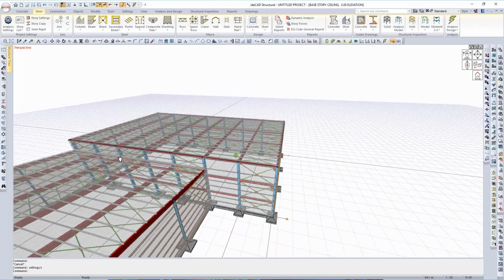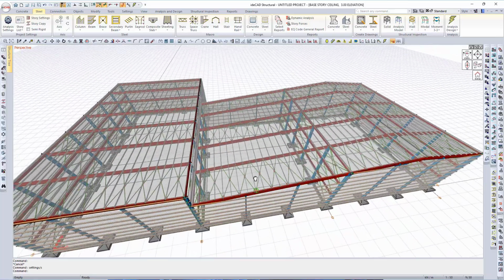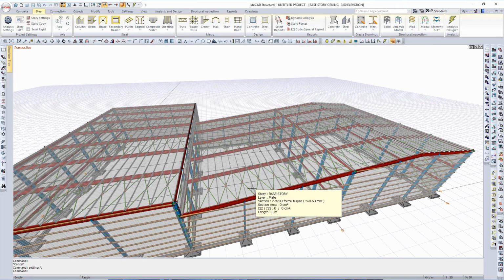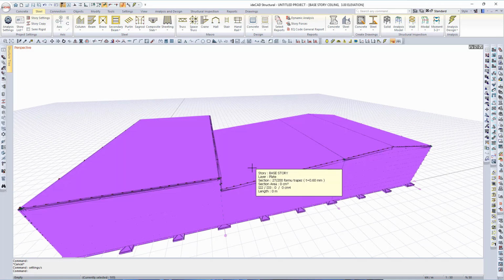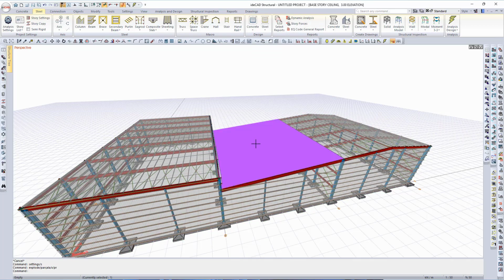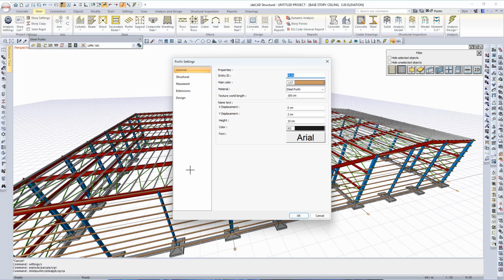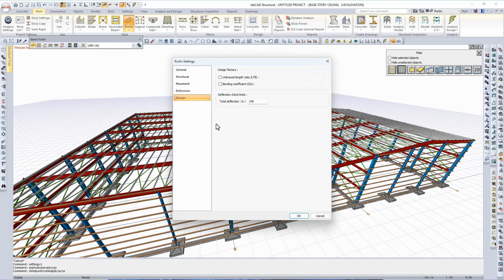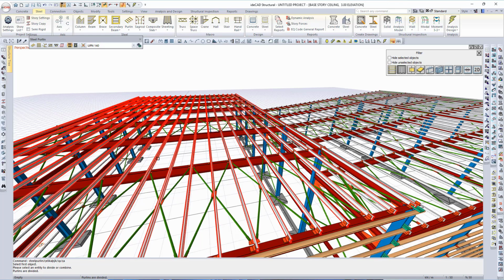As I mentioned at the beginning, the hall macro lets you quickly model the outer frame. To start modeling the internal parts, you first need to explode the macro. To do that, I selected the macro, right-clicked, and chose the Explode command. Now, all elements, like purlins, beams, columns, and bracing, are available individually, and you can edit them one by one. You can adjust the purlins, edit their connections, or split them at intersections. These edits can be made in both 3D and plan views.